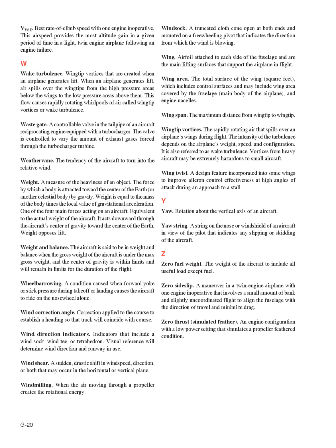Zero fuel weight. The weight of the aircraft to include all useful load except fuel. Zero side slip. A maneuver in a twin-engine airplane with one engine inoperative that involves a small amount of bank and slightly uncoordinated flight to align the fuselage with the direction of travel and minimize drag. Zero thrust, simulated feather. An engine configuration with a low power setting that simulates a propeller feathered condition.